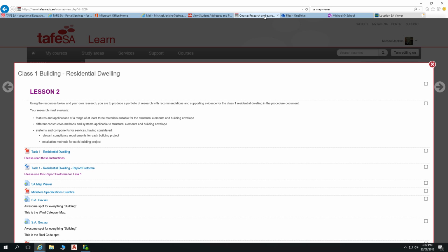Last week we covered predominantly timber framing, touched a little bit on light gauge steel framing as well, and we'll touch again on light gauge steel framing further on, because that's also an important aspect of commercial construction. I don't know what these walls are constructed of, but I would hazard a guess that it's Rondo steel framing in behind that. They wouldn't have used timber. So that is the mainstay of a lot of your non-load bearing walls in commercial construction.